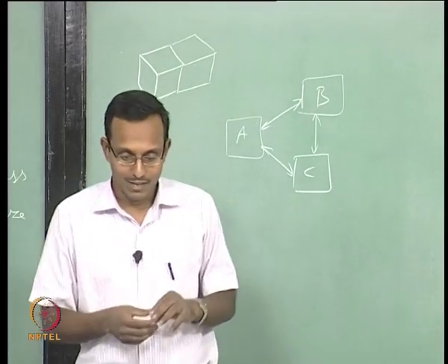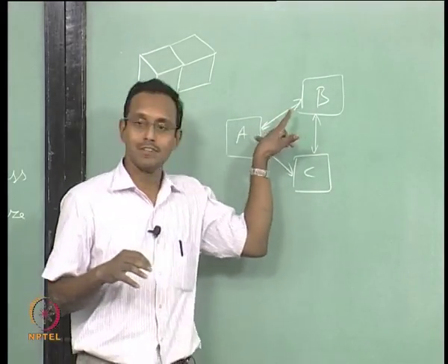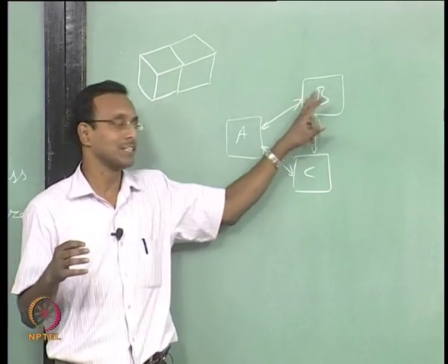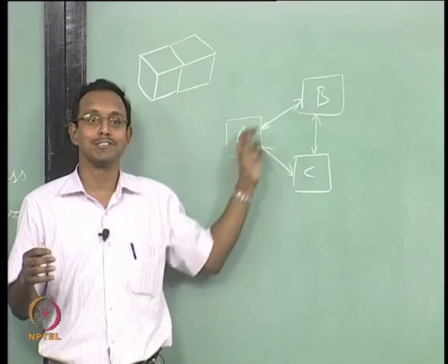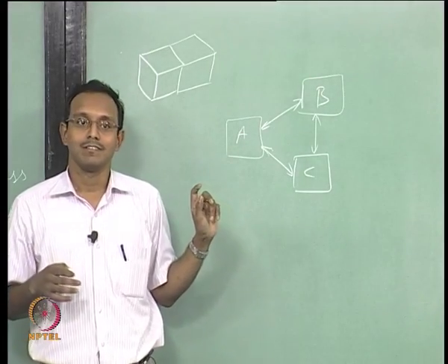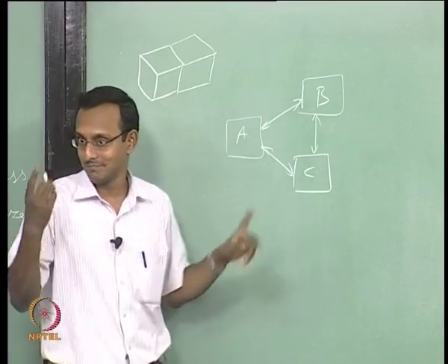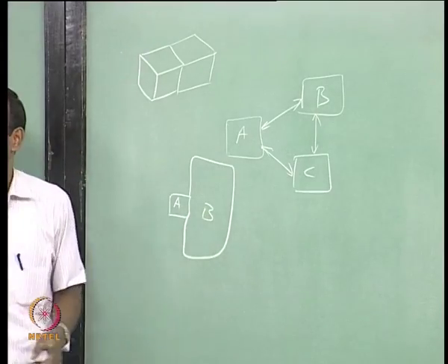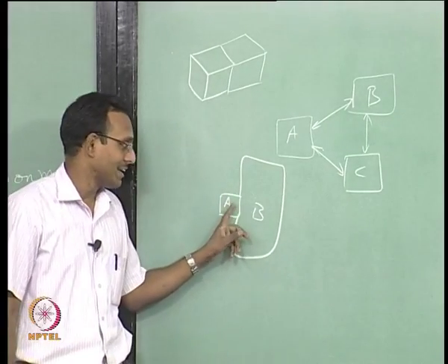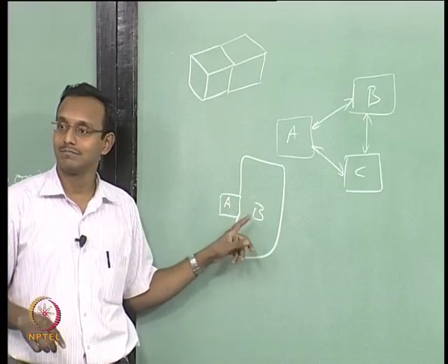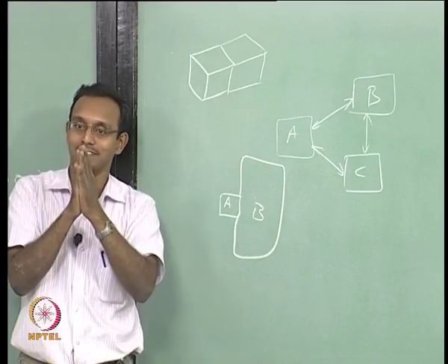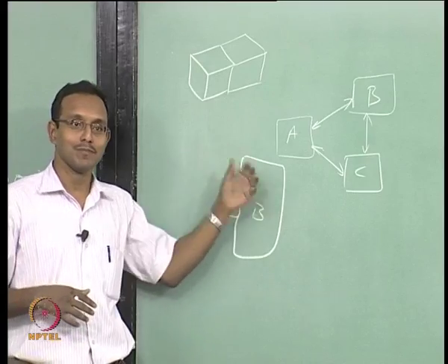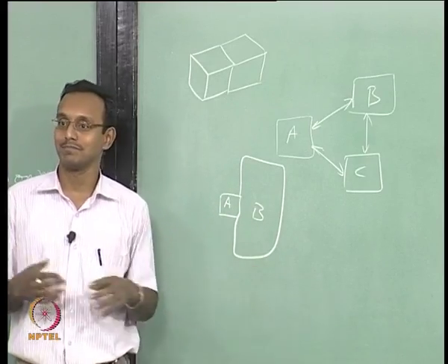That is another way of interaction with energy, that is thermal interaction, this is mechanical interaction. Okay. If I define that, then I ask for mechanical equilibrium. Now I can tell these two will be in equilibrium if the pressure of A and pressure of B are equal, then they will not apply force on each other. Okay. You guys see that? It does not matter what the volume is. I may have a case where A is a small system, B is a big system. I put them together, they do not interact mechanically as long as the pressures are equal. They will not push against each other, or they are pushing equally, nothing happens. Pressure times area is your force, forces on both sides are equal, that is your mechanical equilibrium.